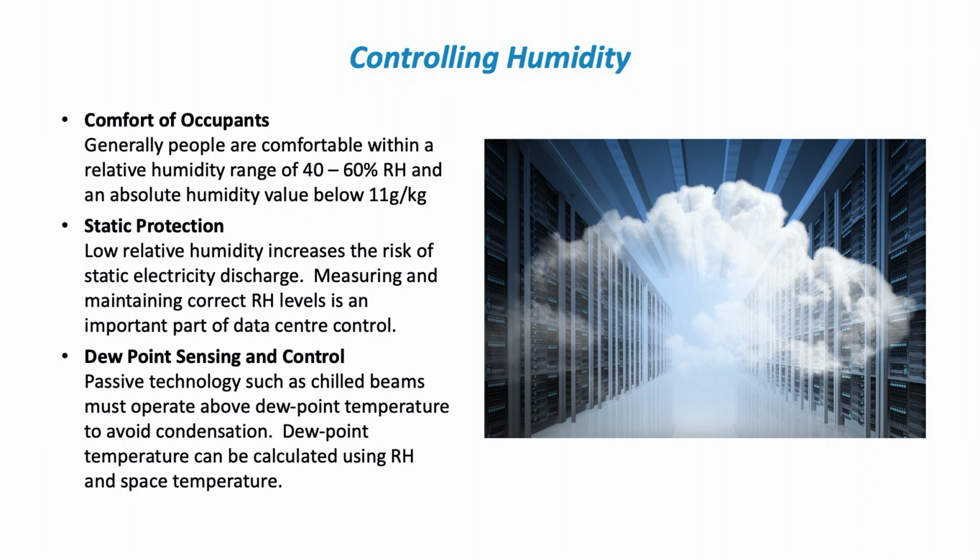So in data centers, oddly, we tend to find a need to humidify the space, to actually add humidity to the space in order to make sure that we don't promote that static discharge. The humidity itself is not what causes the static discharge, but if you get a buildup of static electricity, it is more likely to arc if you have low relative humidity.